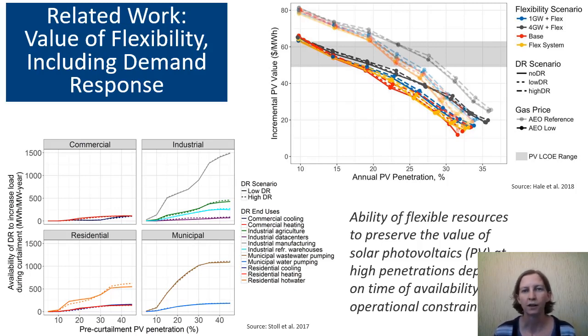By knowing how your load divides up into sectors, subsectors, and end uses, you can think through which of those components might be able to be operated flexibly to help balance the system by either shifting energy use in time or just reducing peak loads.